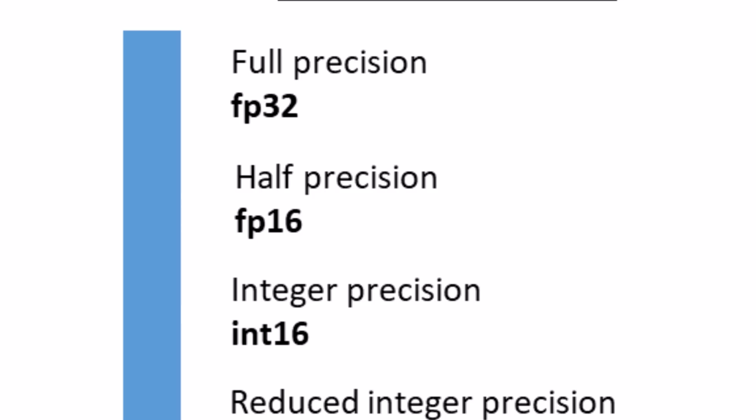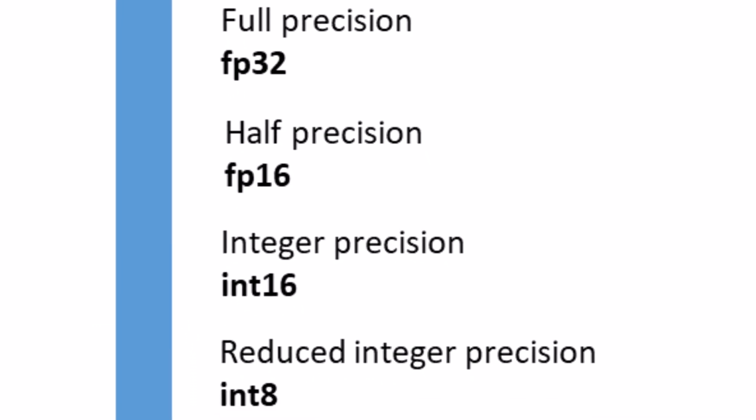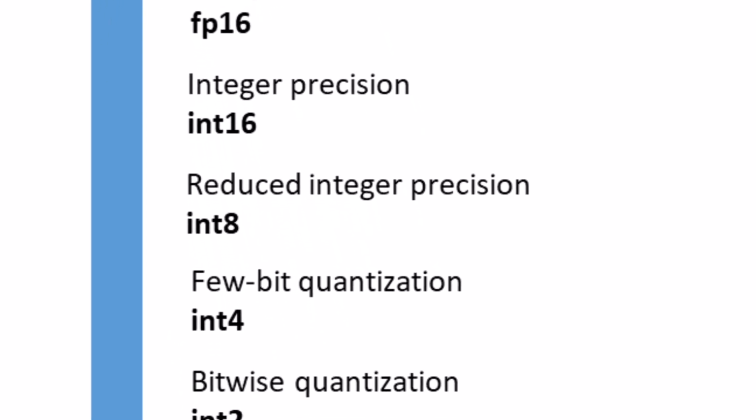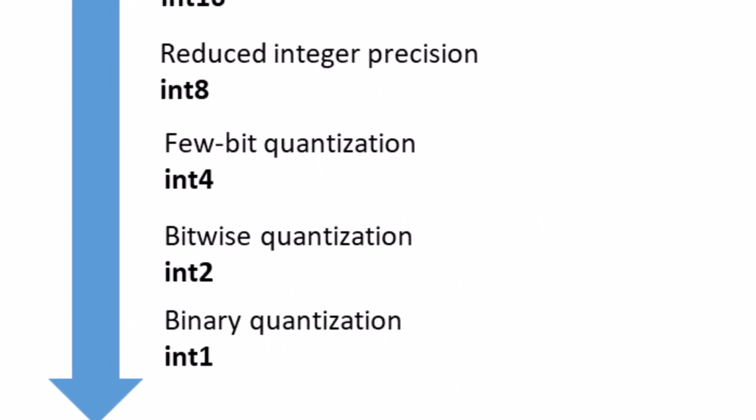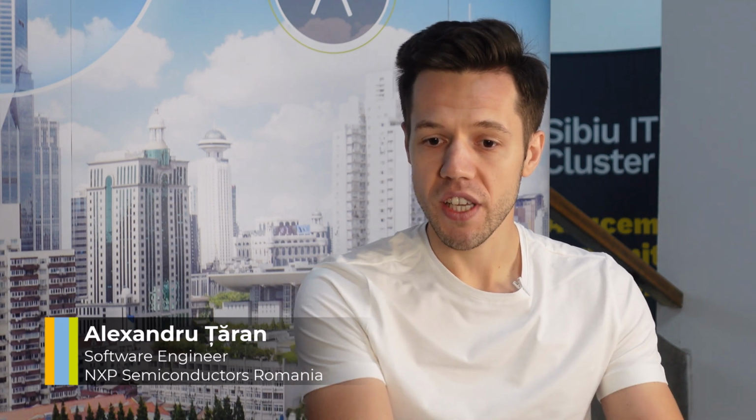For quantization, as you said, we can quantize to different target precisions. For the inference part, we win on the memory that we can fit, but also, in an embedded device, we have the memory and the compute units. Having the network smaller helps when we bring the weights from the neural network into the compute units. We need less memory bandwidth for that. Right. And on the compute side, doing the operations in integer is faster than doing floating point operations and more efficient on the energy side.